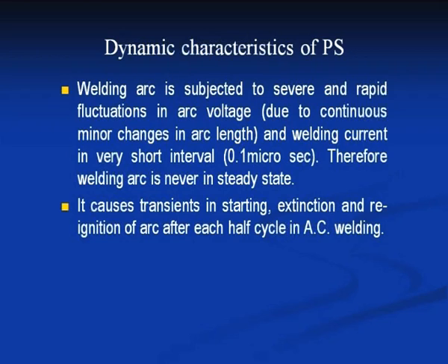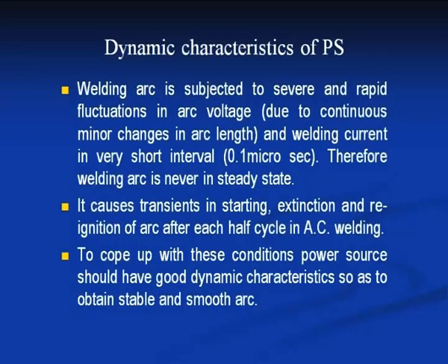To cope with these situations and the fluctuations in the welding arc, where even a small change in arc length can lead to a change in the welding current, it is necessary that the power system responds very rapidly to the changing conditions during the welding.